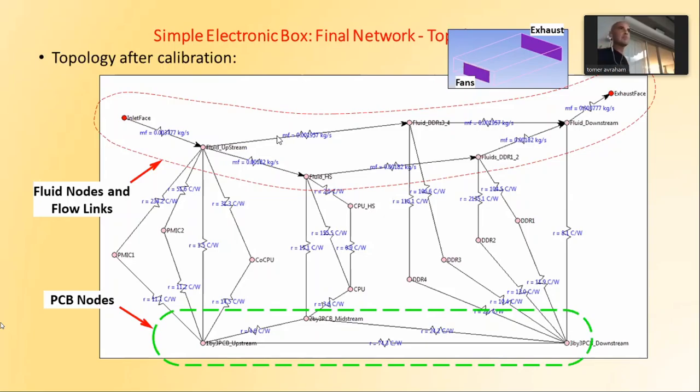SimCenter, even in Star CCM, has a ROM configuration, which means that they'll tell you to choose for yourself 3 points of operation for the fan, or choose 16 of them, choose 16 temperatures, choose 16, I don't know, ambient conditions outside of the box, and then it'll start running the reduced order model.